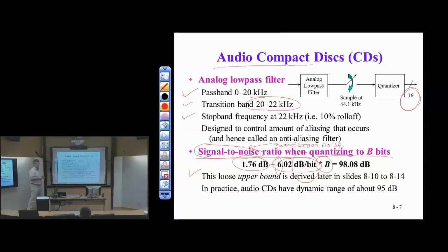So I get about 50 dB of SNR, or probably less than that. It's an upper bound. It won't be more than 50. Or if I tell you the SNR in the channel, let's say I measured the output of an equalizer, is 50 dB, how many bits can I handle of PAM? 8, but no more. So it works both ways.